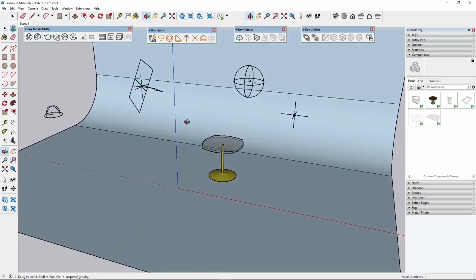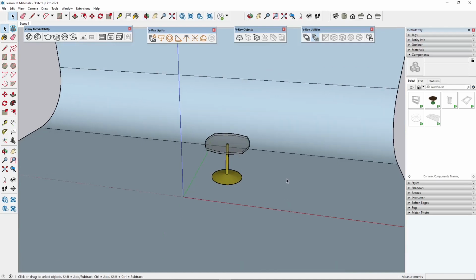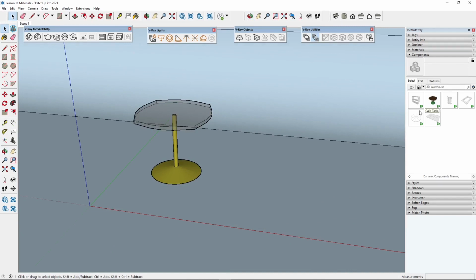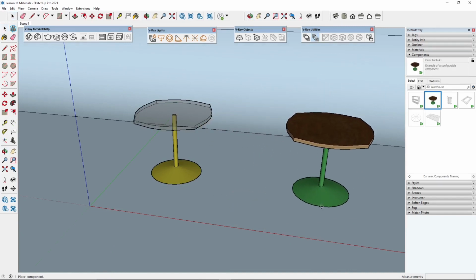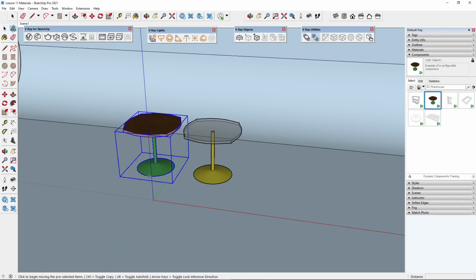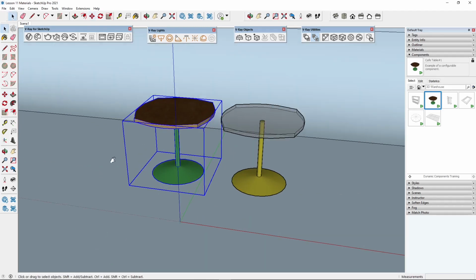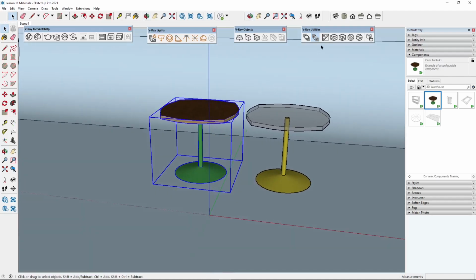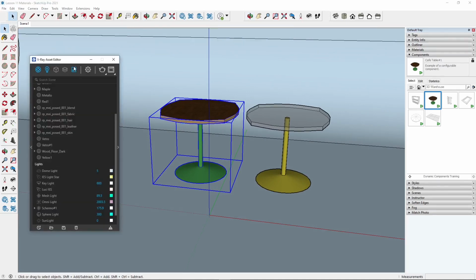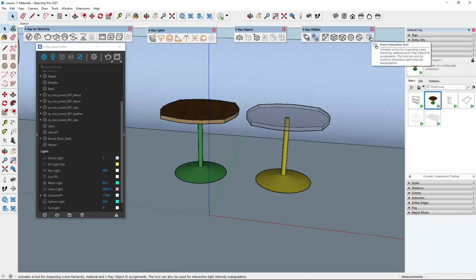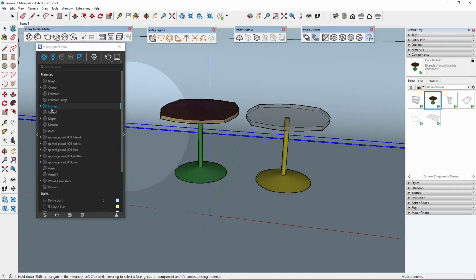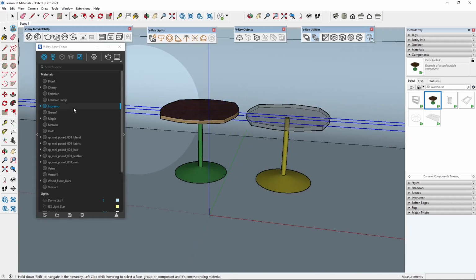Also, I'm using the scene that we used in the previous videos with the lights, but I'm gonna hide the lights right now. And I will click this coffee table here and place a copy. There you go. So the first thing we can check is the materials that are already applied to the object. So if I go into the VRAY asset editor, I can use this scene interaction tool right here, and I can click on a particular surface and find out which material has been used for that surface right there.